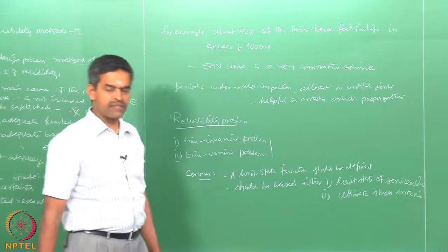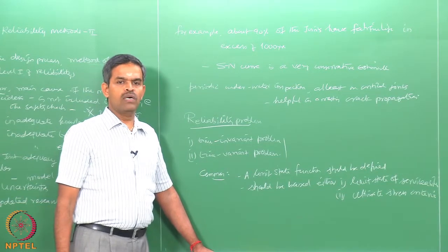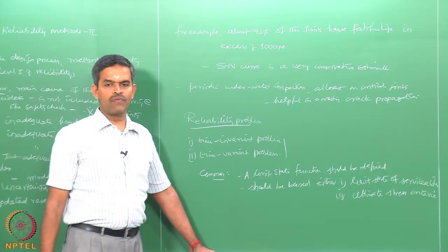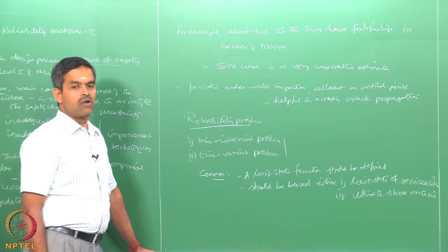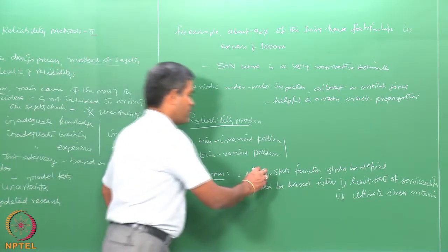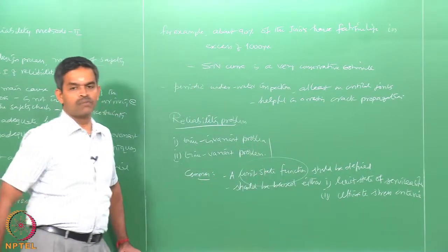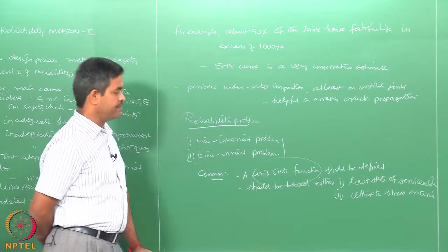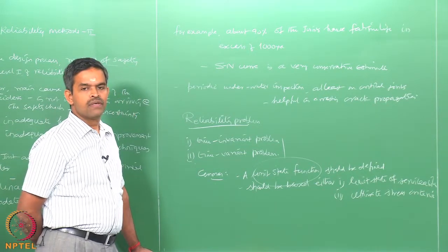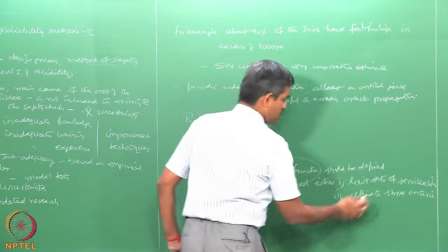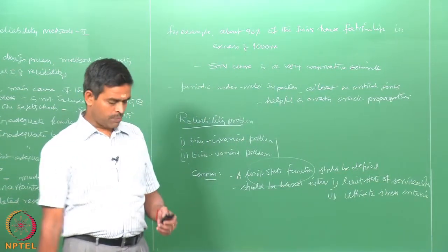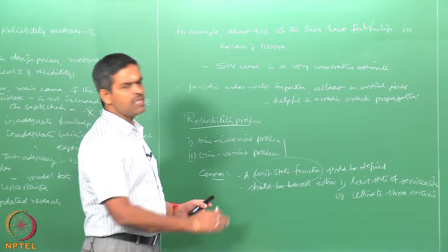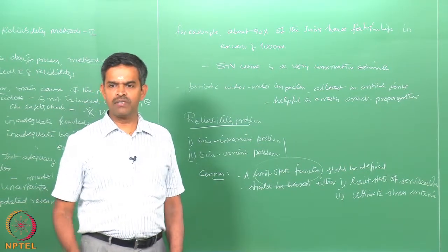So, one has got to prefix this before we do a failure analysis or probability of failure of any specific function, not the structure. So, the limit state function or the probability of failure of this particular function or probability of this function falling in the failure domain can be assessed when one of these prerequisites is available and applicable to the problem of our interest. Therefore, reliability problem aims to determine the probability of limit state failure.